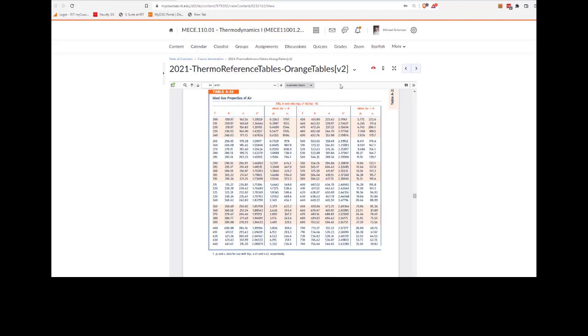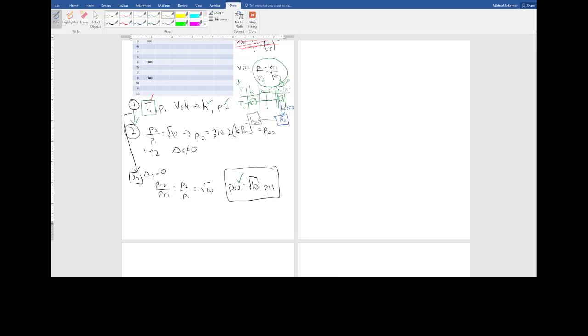So now I'd look over here. PR 4.38 is going to be somewhere in between these two. So I'd find that value, and then I'd have to interpolate backwards over here to find H. Does that kind of make sense? We're going to do a lot of that in this problem.